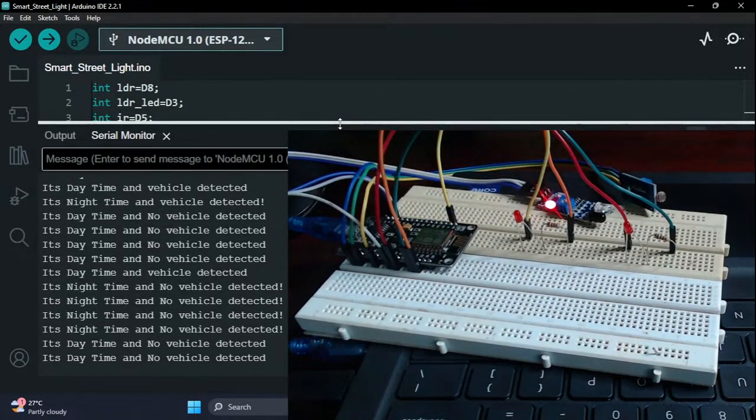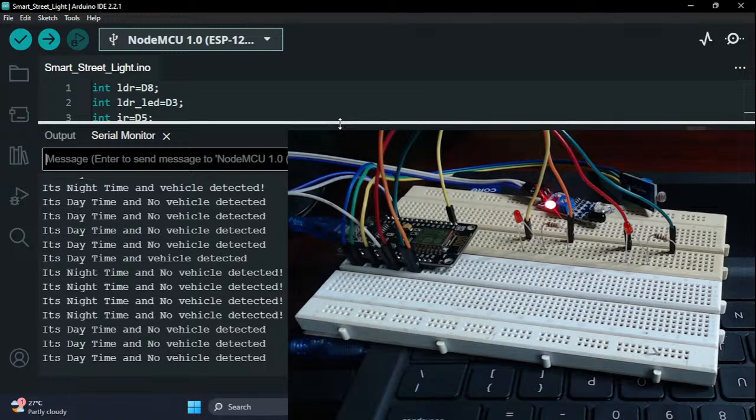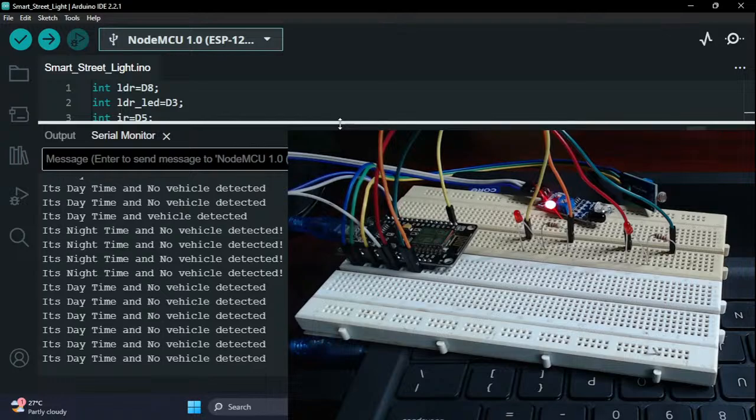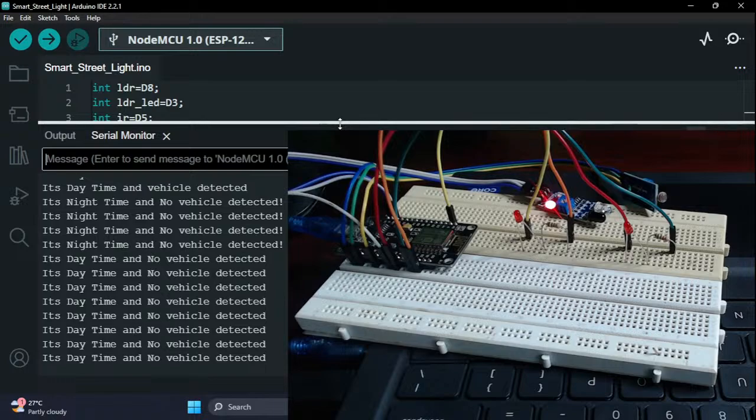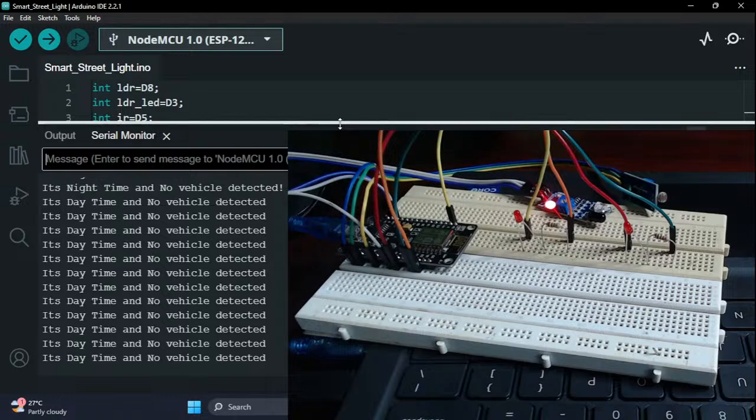I pressed the flash button and reset button multiple times, and finally it works. I also left one port and I tried with that particular port. Now the output came. Maybe there is some issue with my port, I think, or I don't know. Sometimes it works well, and sometimes it gives issues like this. If you face any issues like this, you can just disconnect all the things and connect it from scratch, and try with all the ports you have.